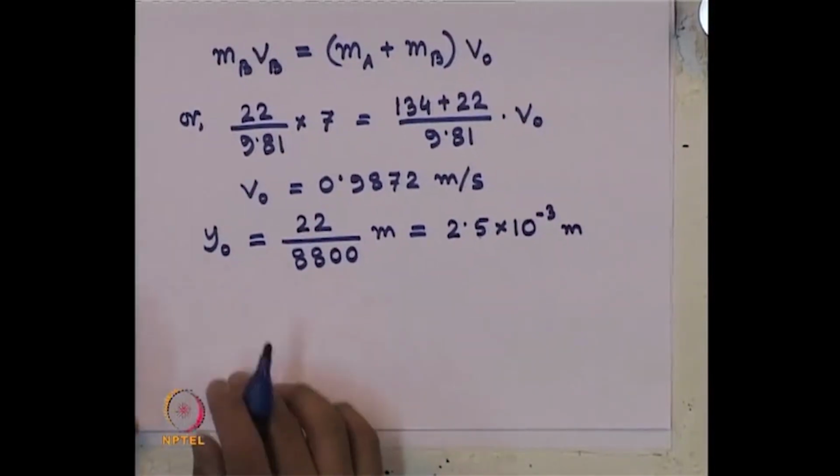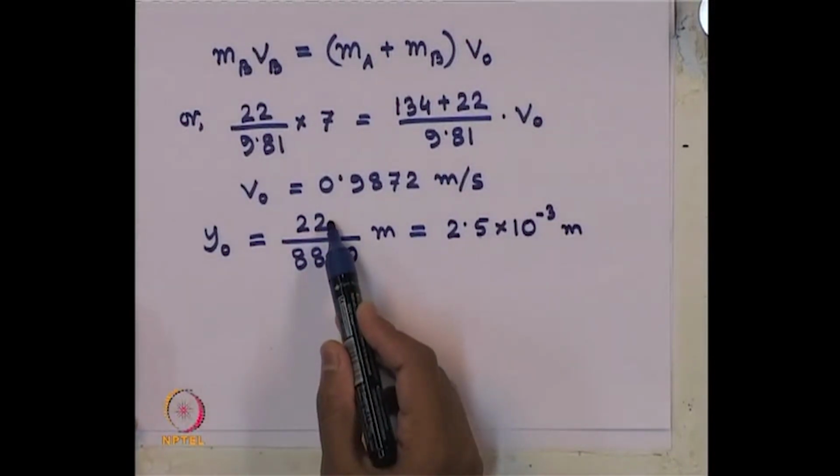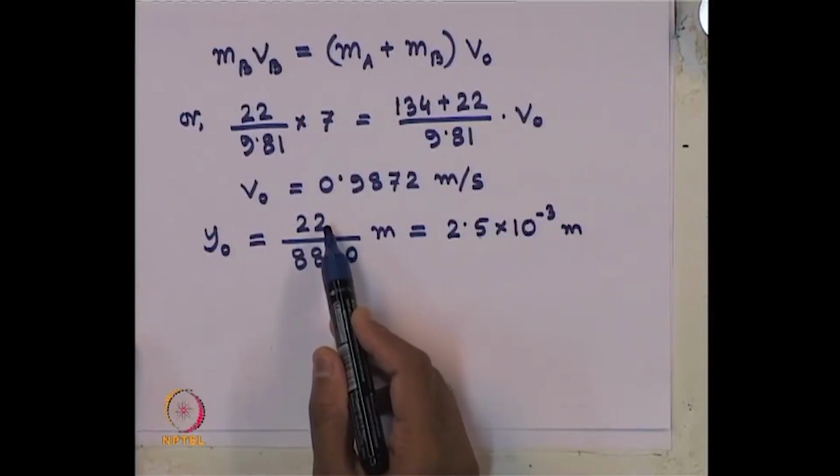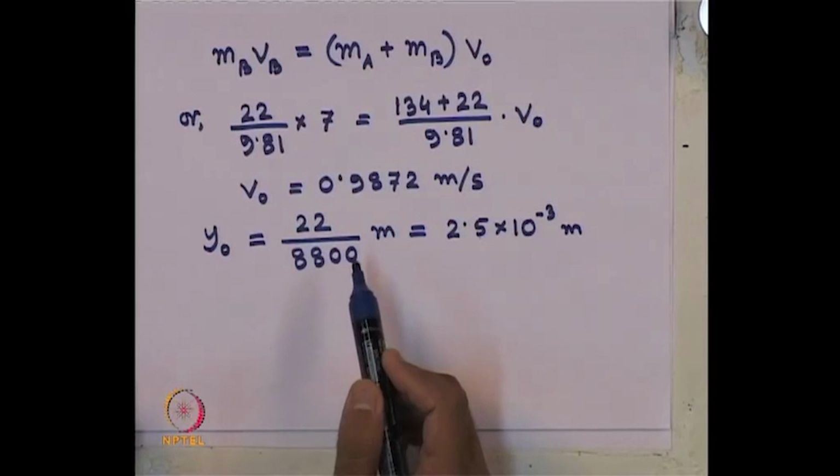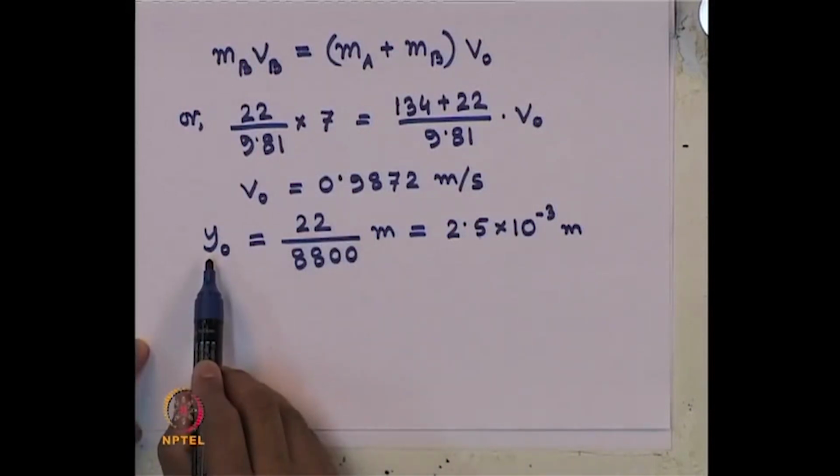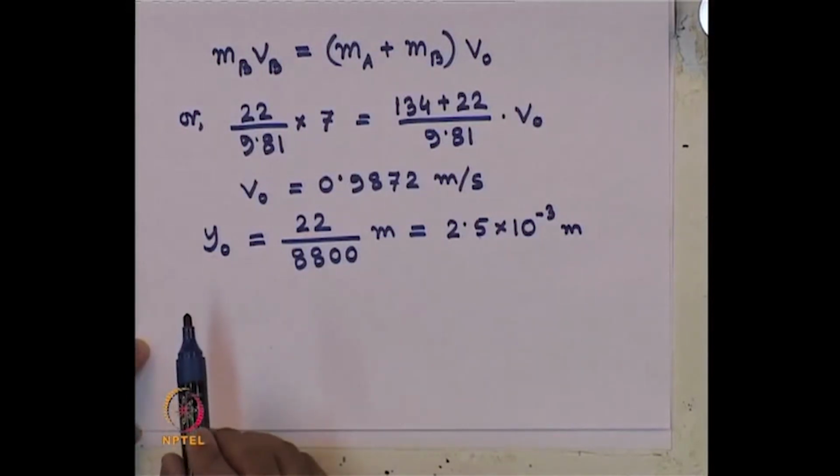So, now the initial condition of vibration is known. This is the weight of the lead pad B, which is causing the vibration which is coming. Why the weight of A is not considered? Because that was already in equilibrium with the spring. So, the initial condition starts because of the impact of the lead pad B coming on A. So, that creates the extra deflection, which is nothing but our initial condition of displacement.